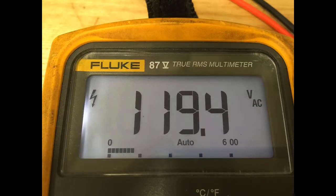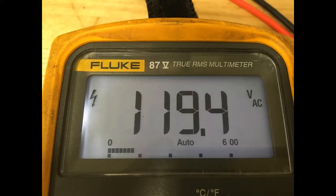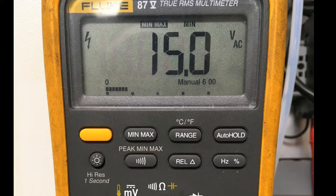When using the meter, anytime the lightning bolt is visible on the left side of the screen, there is a differential of voltage potential greater than 30 volts between the two test points. It is possible to have a dangerous amount of voltage present on a circuit, but because of improper configuration, the meter may not display the correct voltage value. This symbol helps to provide awareness when this condition occurs.